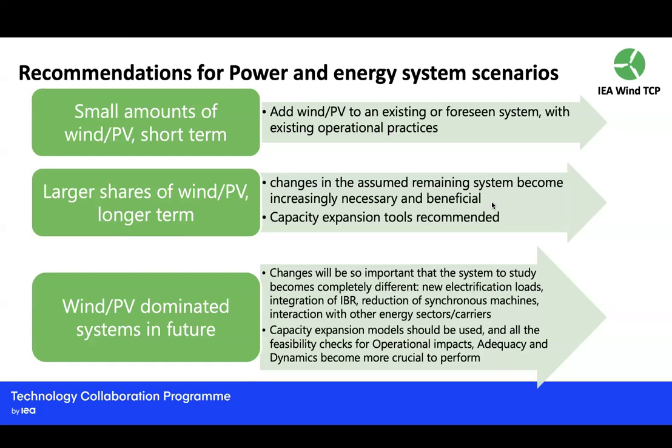As a summary, if you're just looking at small amounts of wind and solar, you just look short term. You just add to the existing or foreseen system and keep it as is. But as soon as you start having larger shares, you need to look at the changes happening in the remaining system, and then capacity expansion tools become recommended. And of course, if you look at a future wind and solar dominated system, you must make your scenarios with capacity expansion tools.